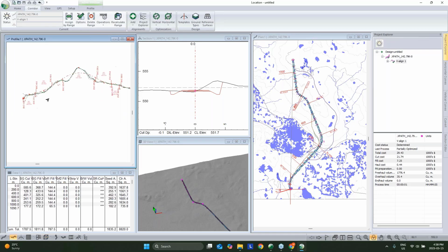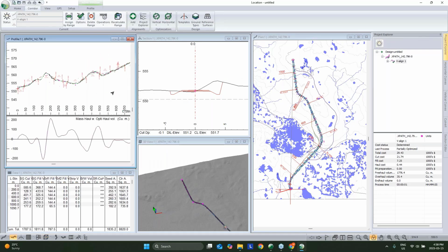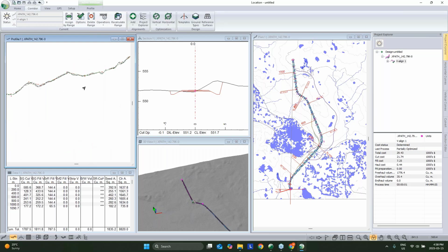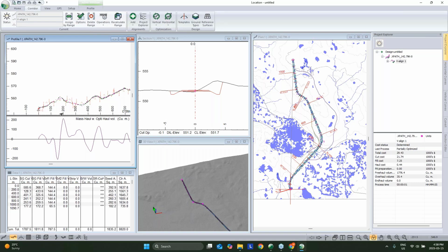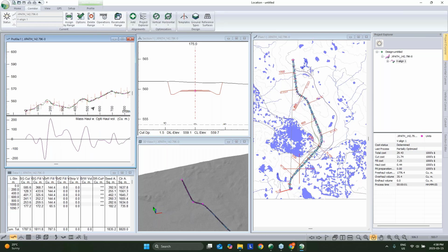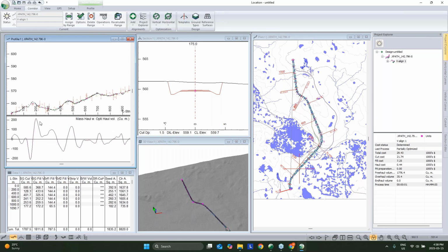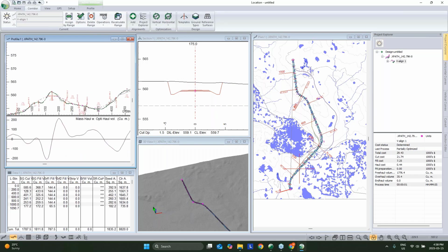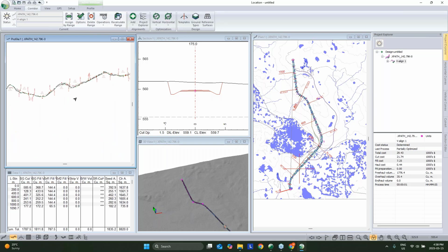And we've got an alignment. So we can see our mass haul is very close to balancing. Our big cuts and fills on this one were 200 cubes going through there. Well, minus 200 to plus 200, so a 400 cube cut, but very minimal, and all that material is getting used for the approaches of it, so very economical use of material.